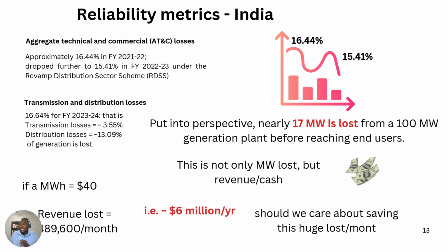So you would understand why we need to modernize. If you modernize using advanced conductors instead of the traditional conductors that we use, we can use the latest conductors that have been researched and produced, and also change some things in the grid that will help us reduce these losses. Apart from technical losses, we also have to remember that there are commercial losses. Commercial losses could be like people stealing power and bypassing energy meters, so you don't actually get revenue from producing the power.